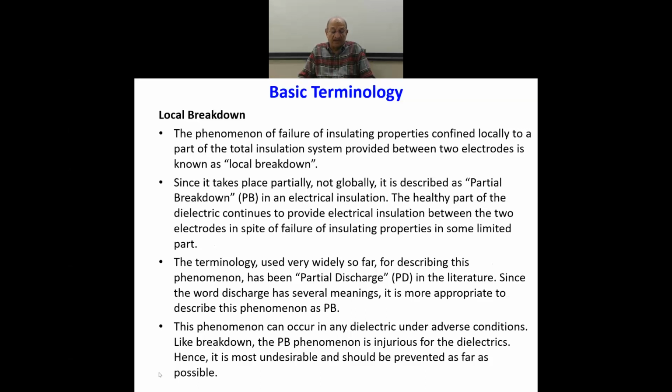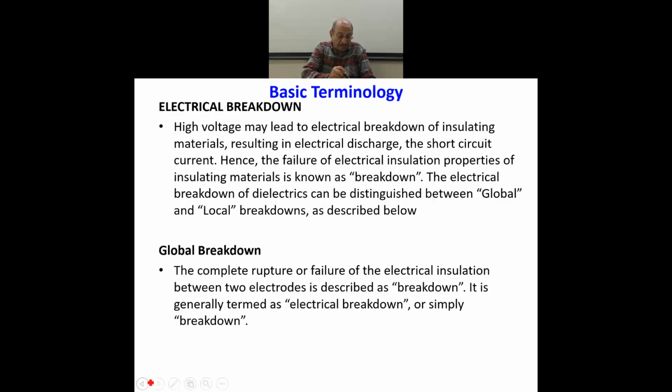And like breakdown, the partial breakdown phenomenon is injurious to the dielectrics, but it may not lead to complete breakdown immediately. If it continues, the complete breakdown may take place over time. Hence, it is most undesirable, because it does weaken the total dielectric, and this phenomenon should be prevented.